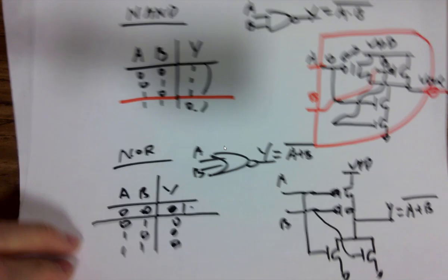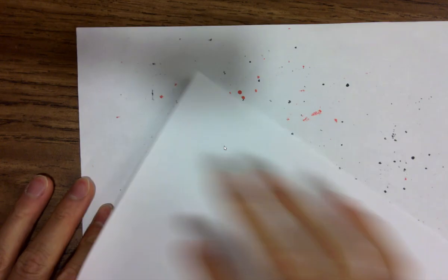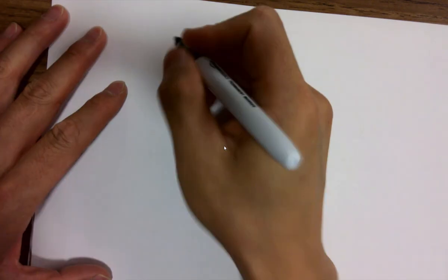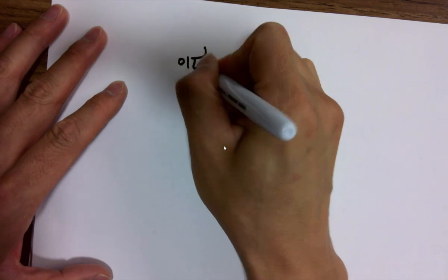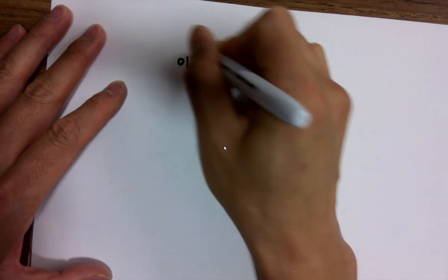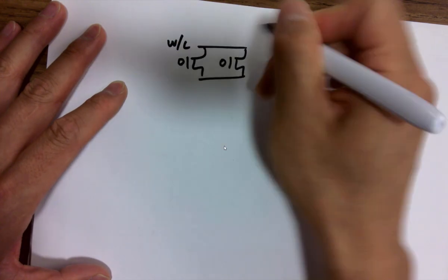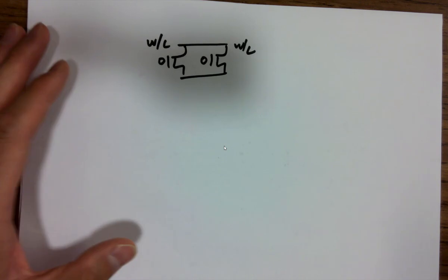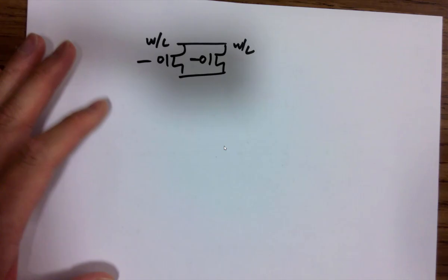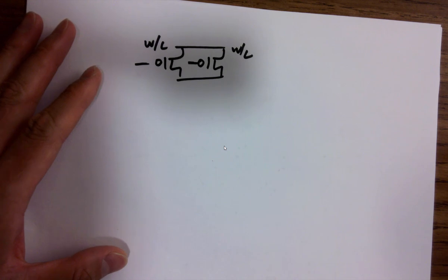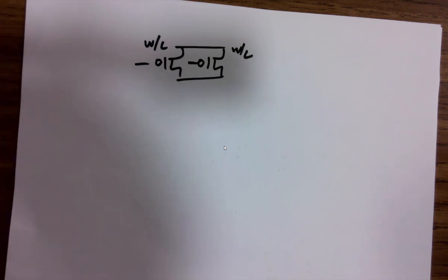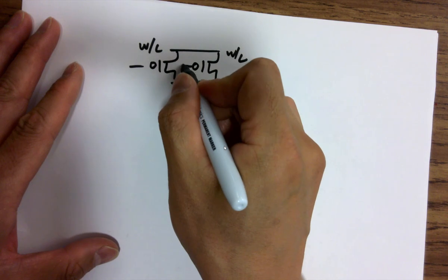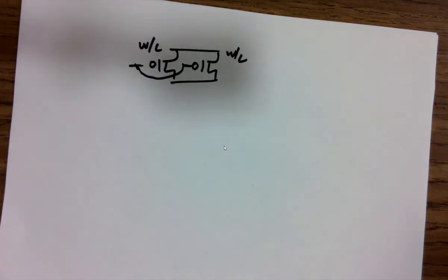So one thing you might see in some of the examples: if I have two PMOSes placed in parallel like this, and each one is W over L, then by default you should consider, if you are not using the gates as two separate signals, for example, they are shorted to each other, the gates are shorted, it's basically one transistor. Just to let you guys know.